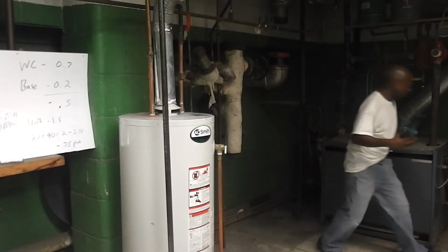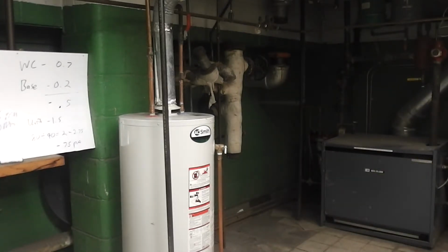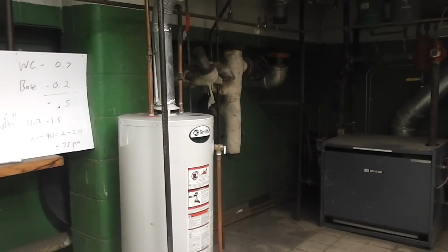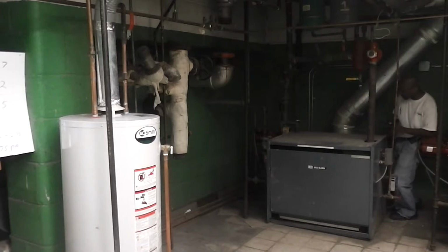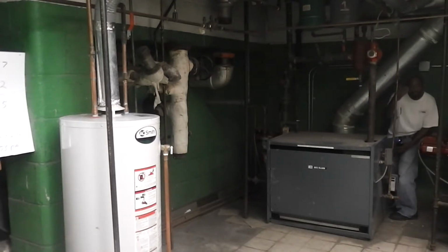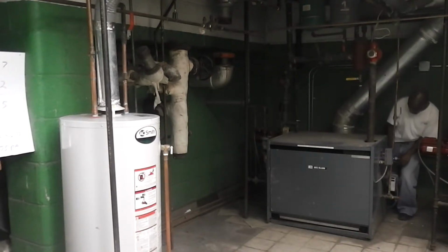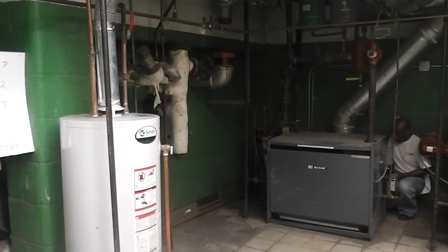So to figure out if this thing's actually drafting or not, I don't know if you can still see me. So far I'm still counting seconds in my head, that same number of seconds. And with the smoke stick, believe it or not, the draft hood is actually down here. So here's where the diverter is at. And pretty much I want to see if any smoke is being blown into my face or is actually being sucked in. It's a good thing this thing comes with a light so you can actually see what you're doing.